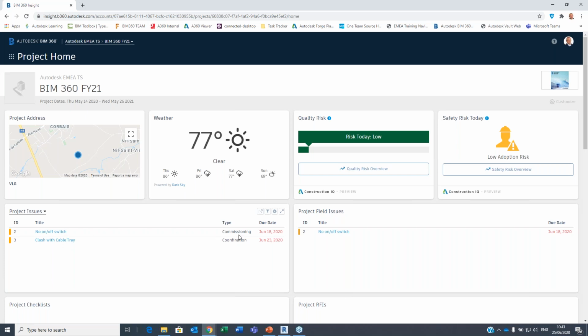Okay, so as you can see, we're assigning types. We're doing that to RFIs. I'm not going to go into RFIs today, but it's more or less the same thing as issues with a workflow attached to it. But essentially, we're filtering data, right? These issues, by the way, can come from the field, so I can have my mobile device and actually flag an issue or indeed create an RFI on my app. It gets synced to the cloud and it will be flagged up in here.